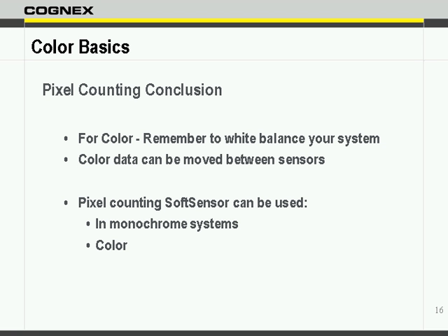So this could also be used for, let's say, presence-absence applications in monochrome systems as well, where we're looking for an area of a particular grayscale intensity. We can also use it and pass it to a filter tool, and we will look at that in just a second, so that we can use it as a thresholding value or an image processing operation.